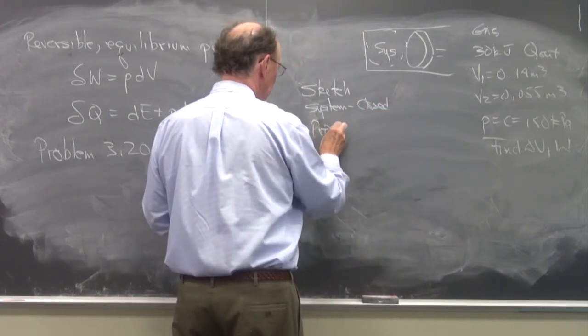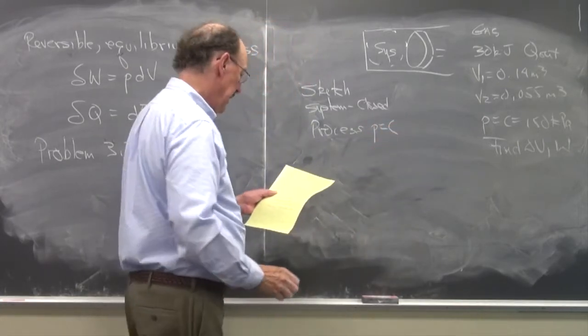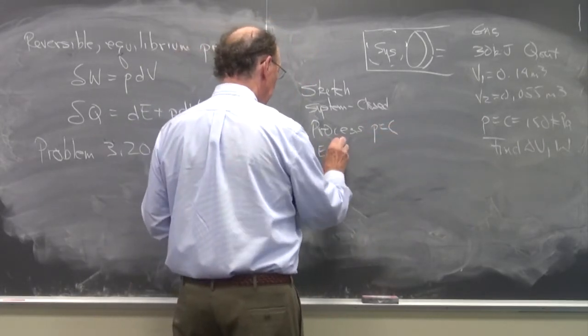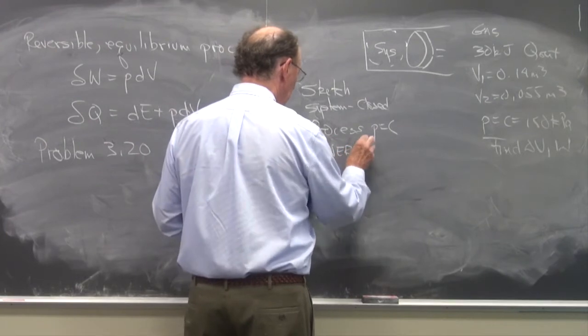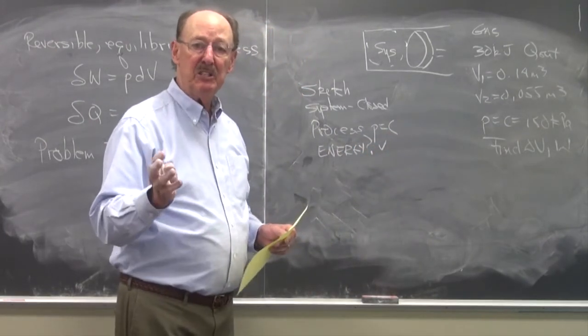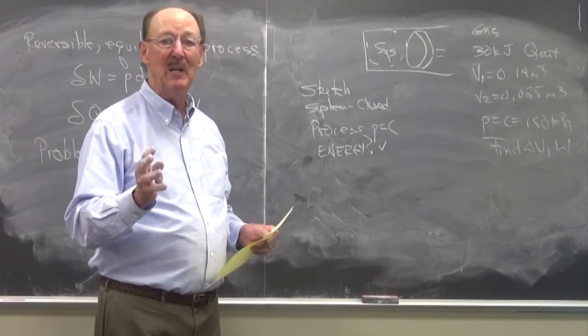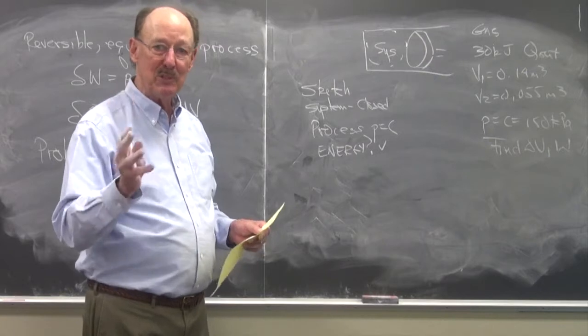Process: P equals C. Is energy involved? If energy is involved, do the first law. Do not tell me you don't know what to do. The next thing you do is the first law.